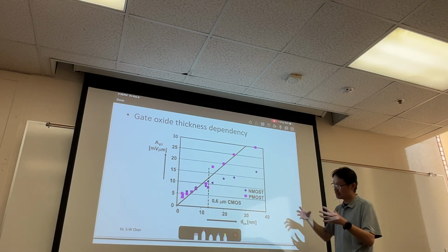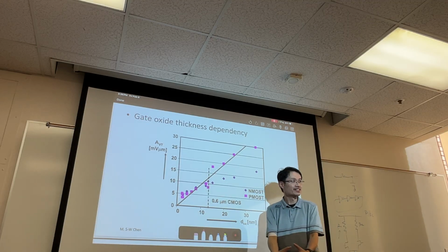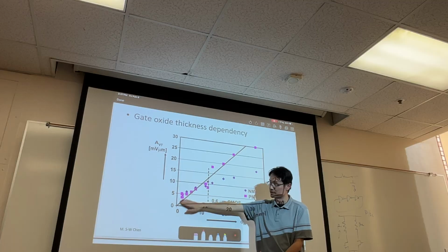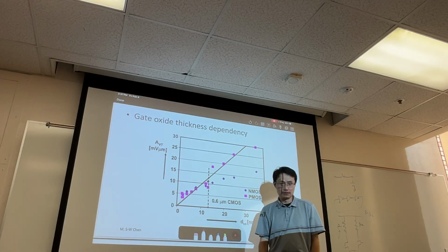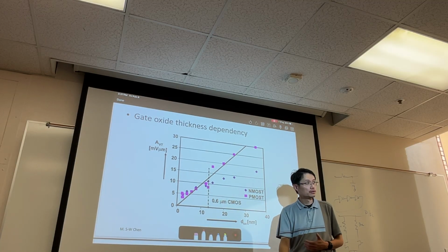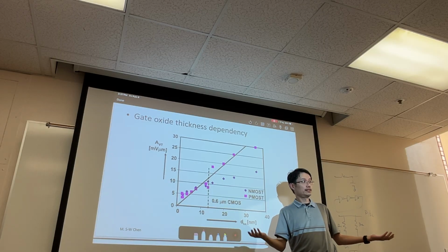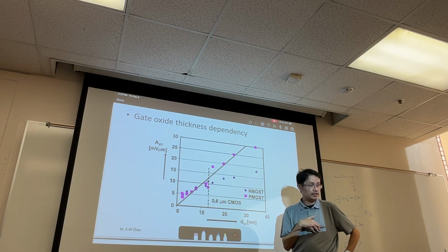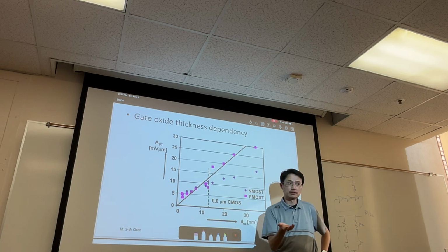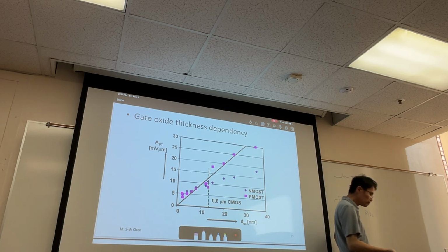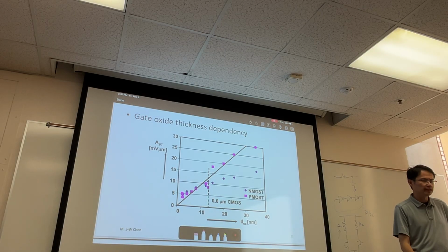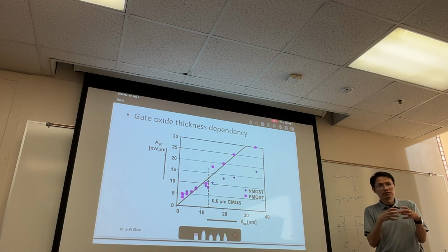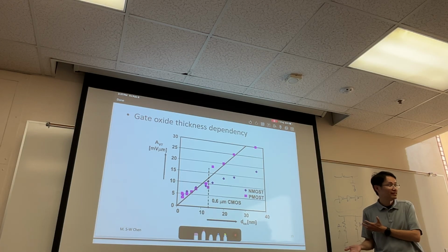Our W and L right now are all scaled down very aggressively, right? But if your A factor does not scale down as fast or even more, then we lose. In the end, we lose. Unfortunately, that's generally the case for us. So that's why people say that when you scale down to a smaller technology node, our analog circuit still looks bulky compared to the digital guy.